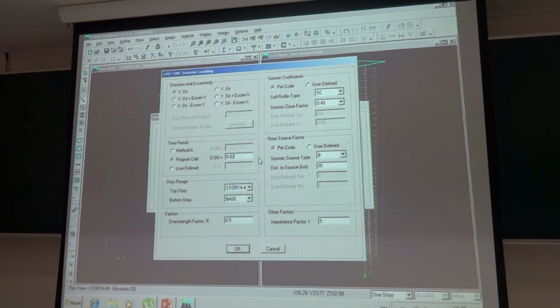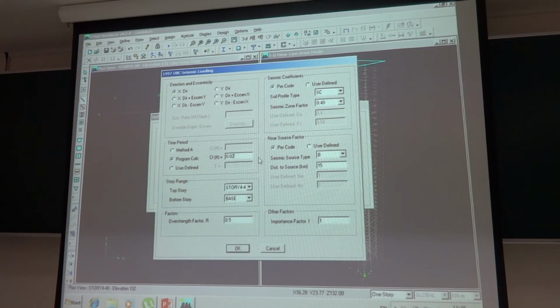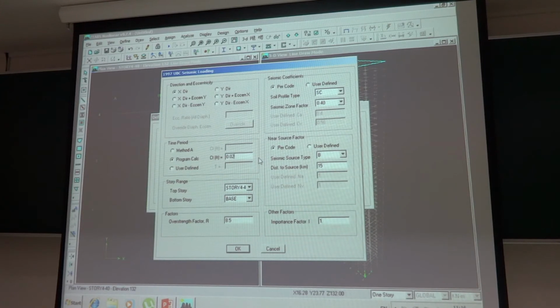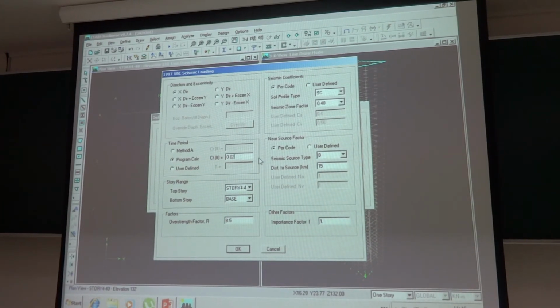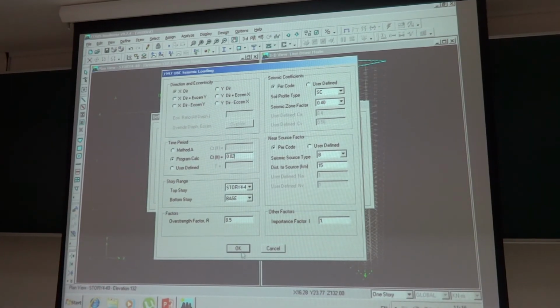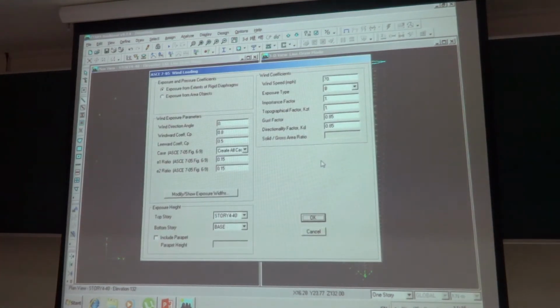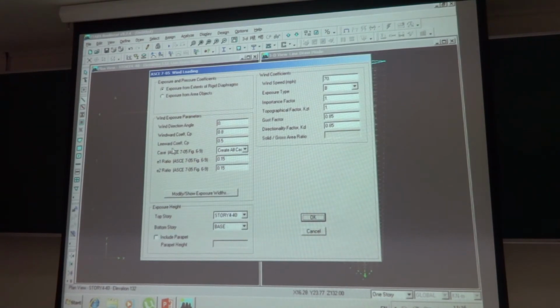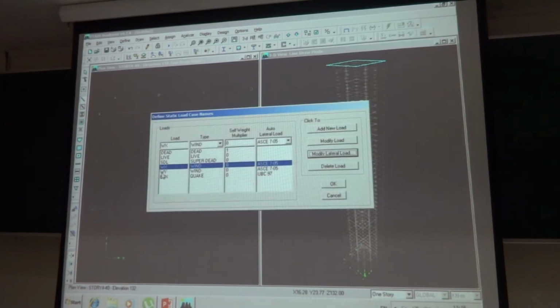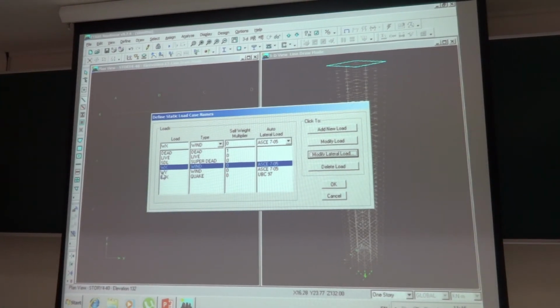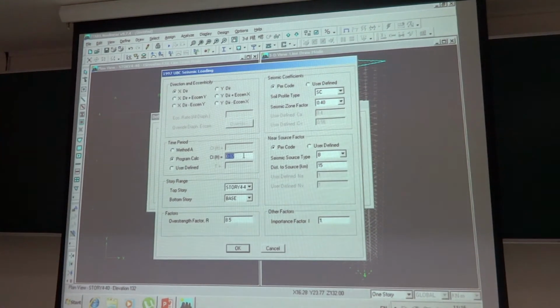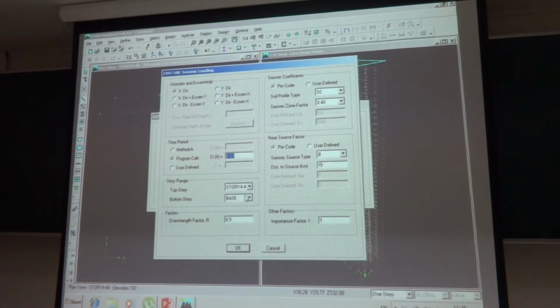So if you use ASCE 7-05 for the wind loading, you go to the wind loading section and read the gust factor calculation and calculate it. Also, the Cp coefficient you can get from the table of ASCE 7-05. For example, here, Cp value, I do not remember the table number. Some already mention the figure number, but you can find the Cp value easily. And UBC 97, same thing. You have to go to the earthquake section and see the parameters. This one for the shear wall building, 0.02, and okay.